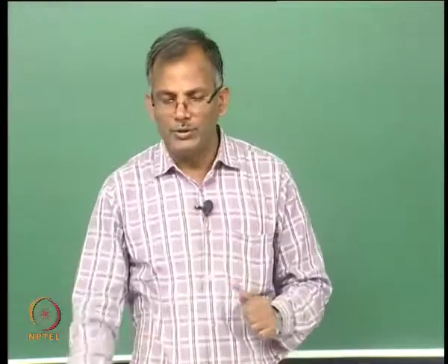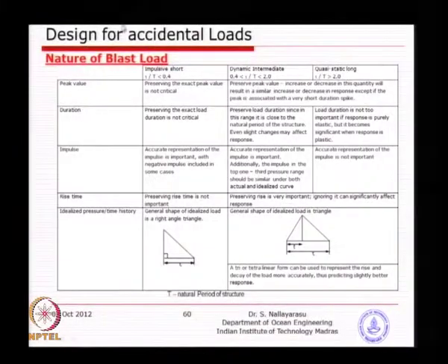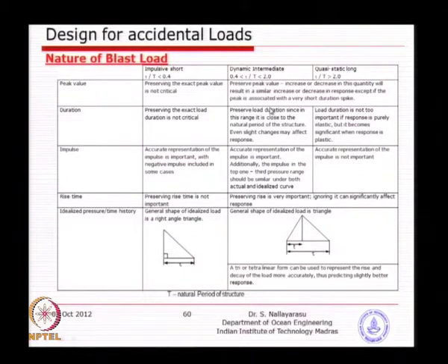So, what we try to do is a single degree of freedom model of the first two items and try to find out what could be the possible dynamic load factor, then apply it to a quasi static model, which is a simple static analysis, increase the loading by that amount and then find out what the response is.